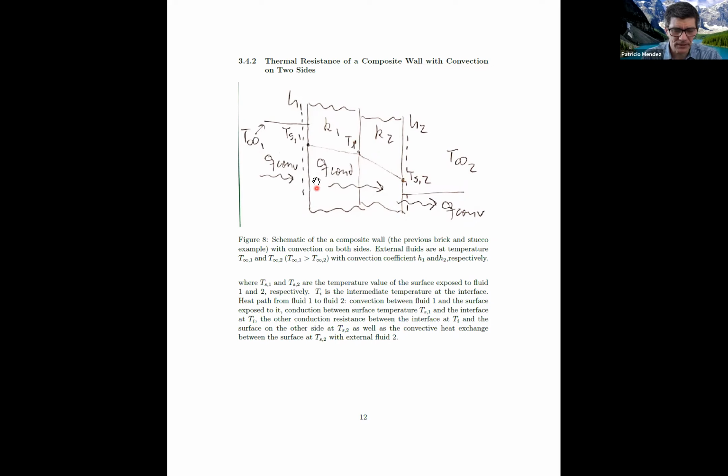Let's also say that inside, very realistically, we have only natural convection, because if everything goes right, you don't have wind inside your house, not in winter. Let's assign a convection coefficient of 10 watts per meter square Kelvin, as we always do. Ballpark, it's not too bad. And outside, yes, we have wind. Because we have wind, we're going to claim that it's forced convection with a convection coefficient of 100 watts per meter square Kelvin. The rest is the same as what we just discussed.